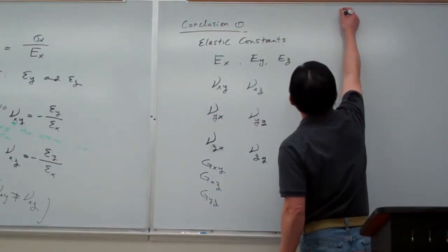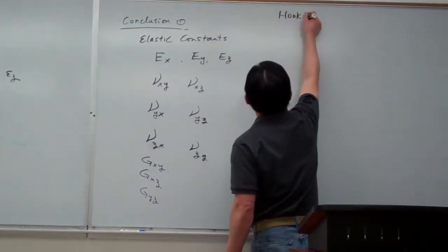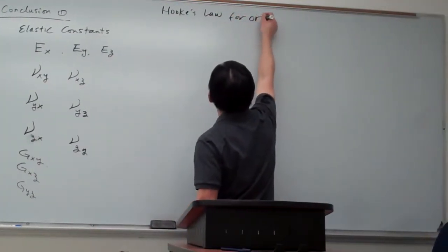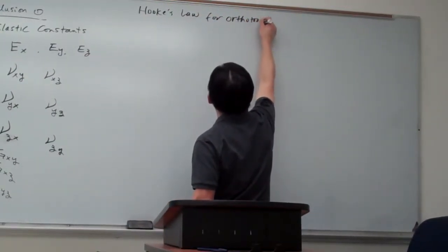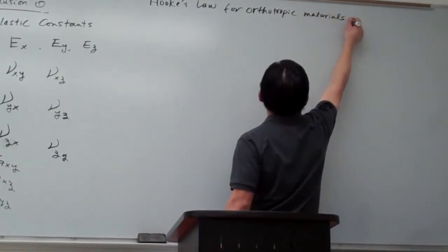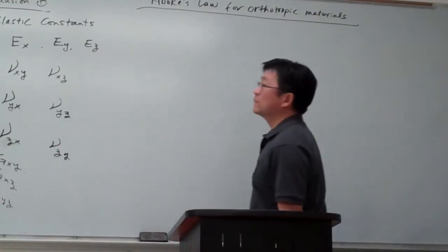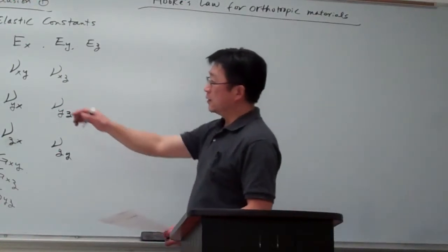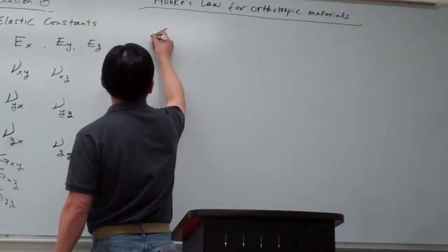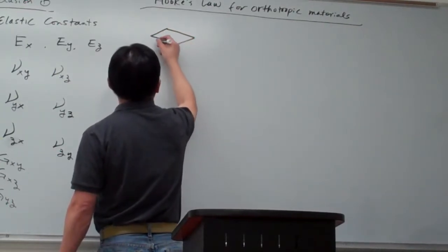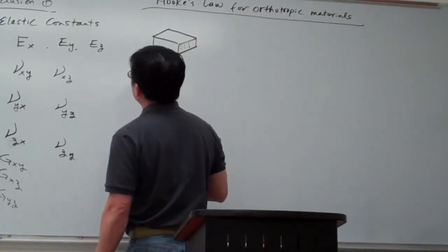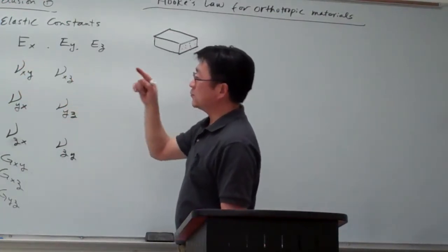Hooke's law. So we can build up Hooke's law for orthotropic materials. And again, we apply the superposition principle. So let us pick up that generic model. Here is the model, and I draw that one very schematically. Okay. So using the same coordinate system x, y, z.